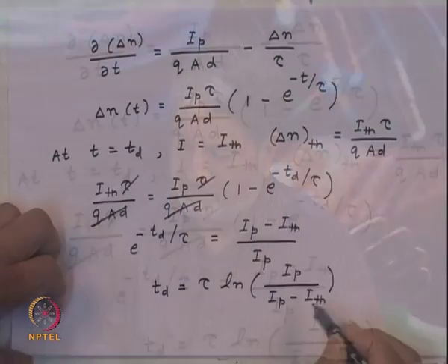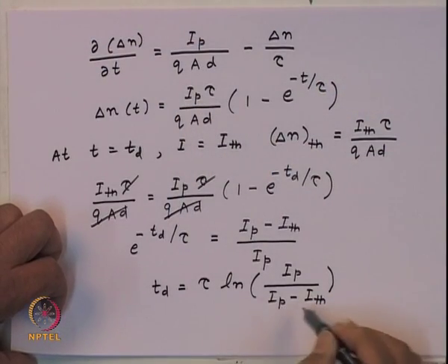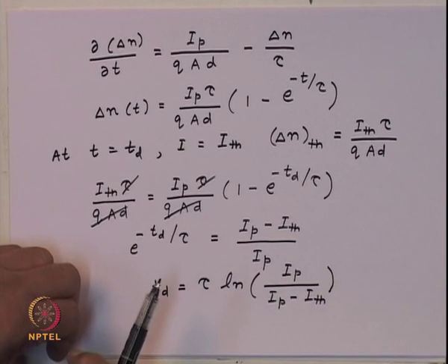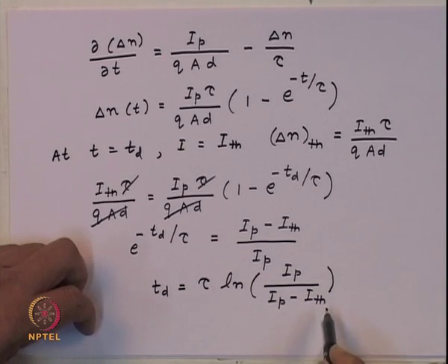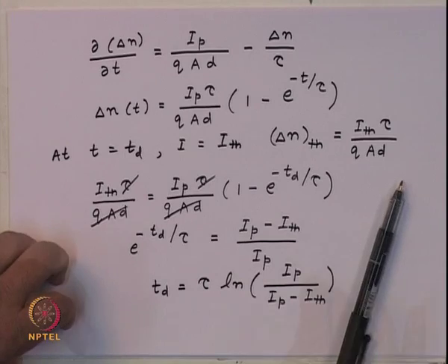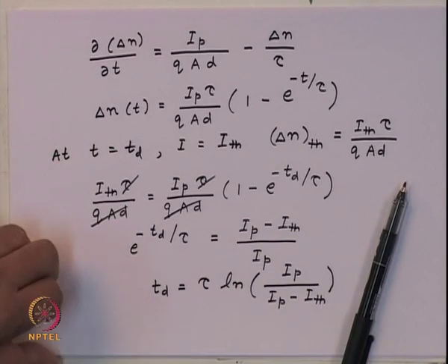So, if you wanted to modulate it at a faster rate, you will not be able to lase it at a very fast rate, because this much time is required to get the laser into action. So, this parameter essentially tells you about the speed of the device, or the modulation speed which the laser would have. Of course, if the threshold current was large, then this quantity will become smaller and smaller, and then you will see that the speed increases, but this quantity essentially goes down.